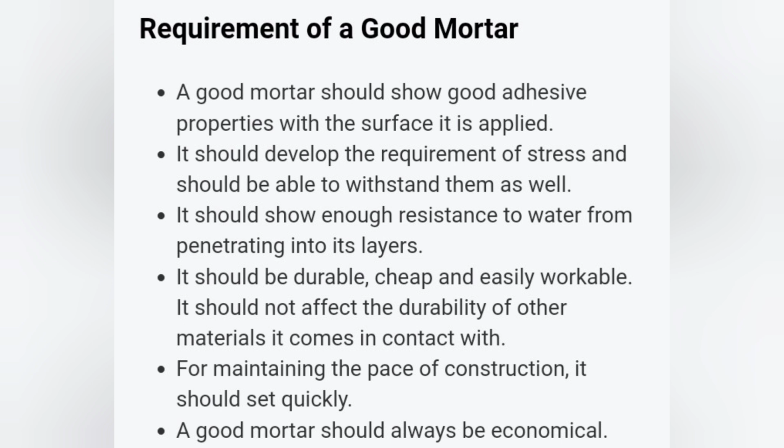Requirement of good mortar. A good mortar should show good adhesive properties with the surface it is applied to. It should develop the required strength and should be able to withstand stresses as well. It should show enough resistance to water from penetrating into its layer. It should be durable, cheap, and easily workable. It should not affect the durability of other materials it comes in contact with.